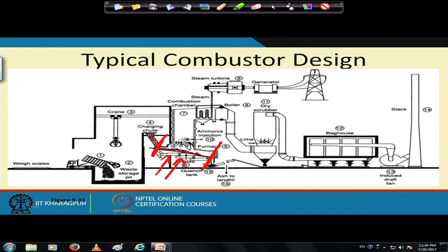The grates are made of material like ceramic, which can withstand very high temperature. So that's where this is burning. Then you have your secondary combustion chamber. So the gas that is going up is heated up even further, so that you have fewer air pollution issues. Then here is your heat exchanger. These are the tubes which have water. It generates steam. From the steam it goes to the steam turbine, generator, and electricity.